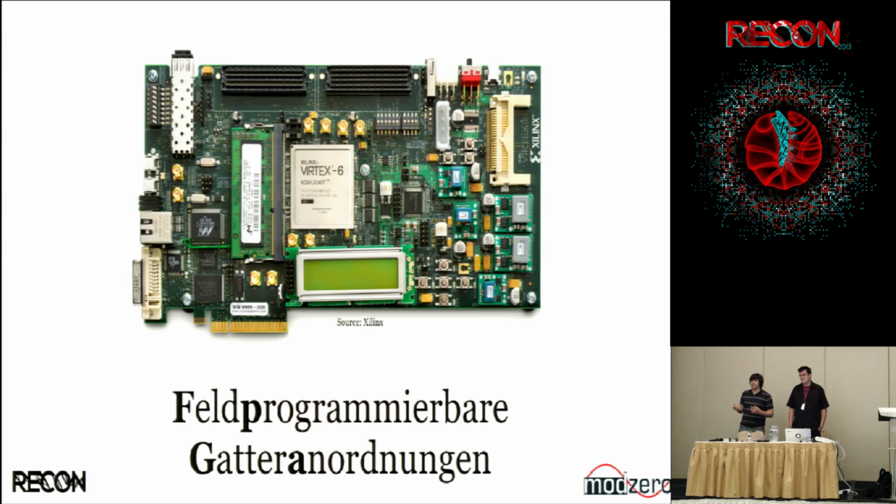So you don't have the software overhead of reading in the pins, writing to memory, etc. You can do this all in a single clock cycle because you write the hardware to have this one purpose, and you make it as big or as small to be able to execute things in a single clock cycle.